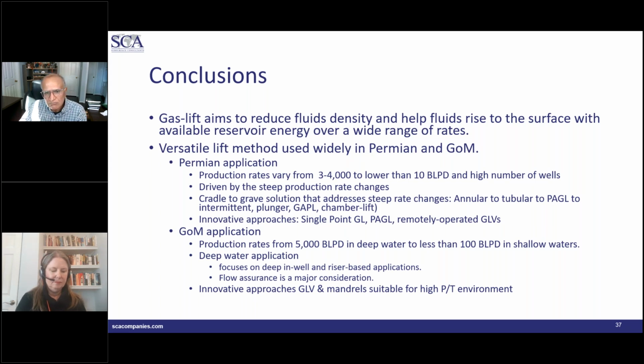Another challenge could be sand and the proppant that comes back. Good news is that the gas lift is not impaired. The lifting ability is not impaired. However, from the facility side, you still have to pay attention to considerations like erosion-related issues, and also, once all of that sand comes to the surface, how to handle it without your systems getting plugged or your separator. So those are the two things that come to my mind.